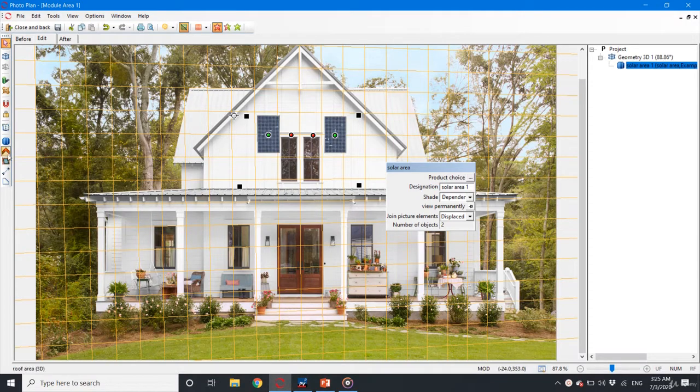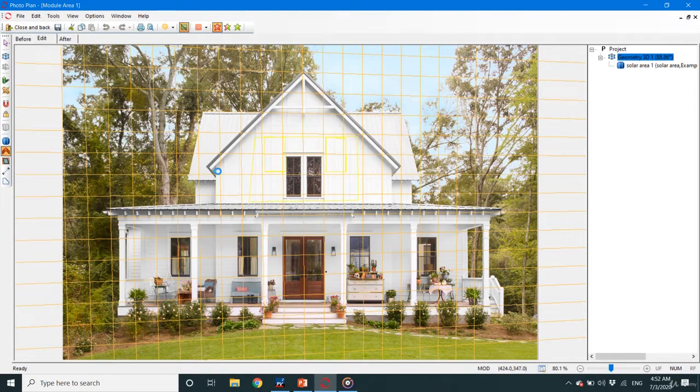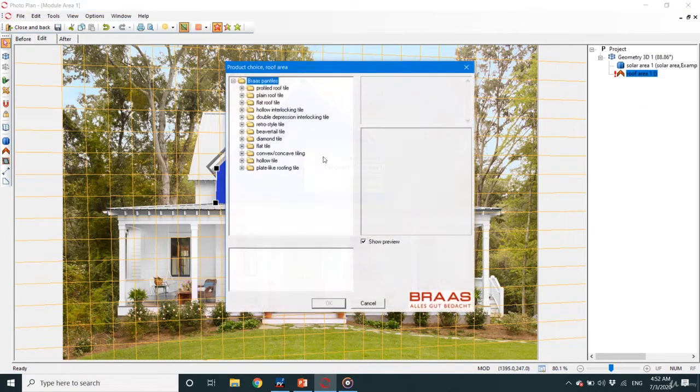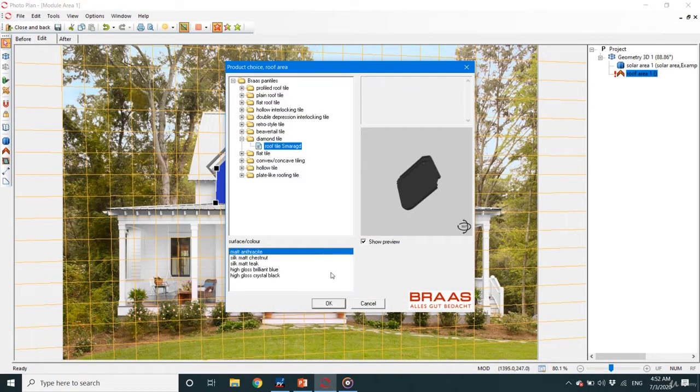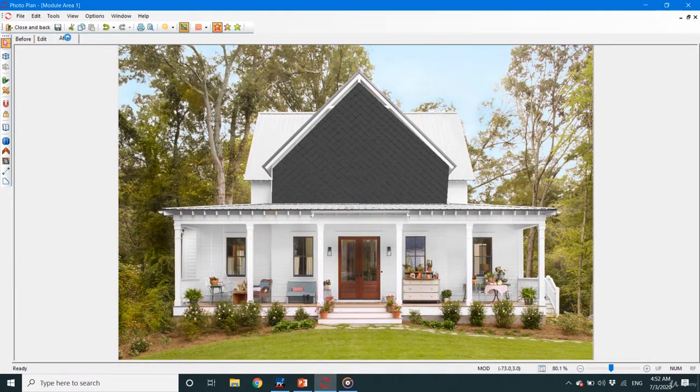You can create a 3D roof in the plane you create. Select the plane geometry, then select the roof. Then drag the lines at the edges of the roof. You have to right-click, then select the tiles used to create the roof. If you go to render, you won't see the panels as they are under the roof.